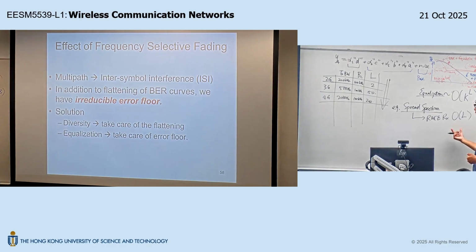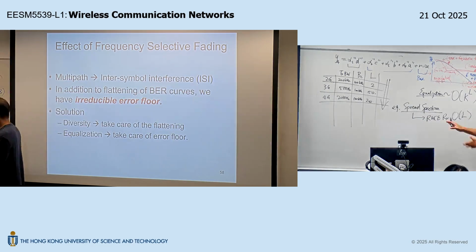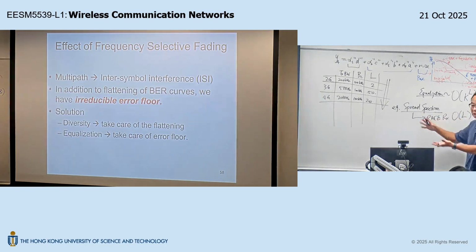The fundamental reason why you have this low complexity receiver that can deal with this ISI problem is not because the receiver is clever. The fundamental reason that it works is because the transmitted signal has some built-in structure, and the rake receiver is just a clever way to exploit that structure. I will talk about the details, and by then you will know what I mean.